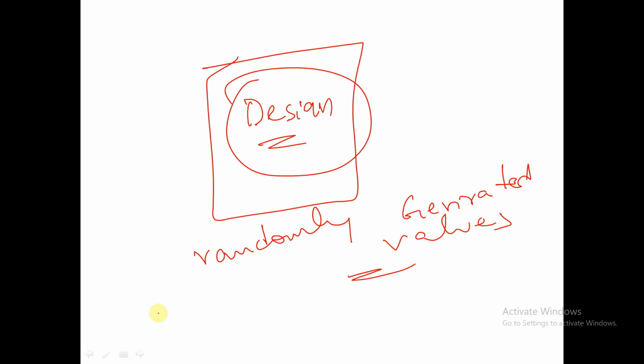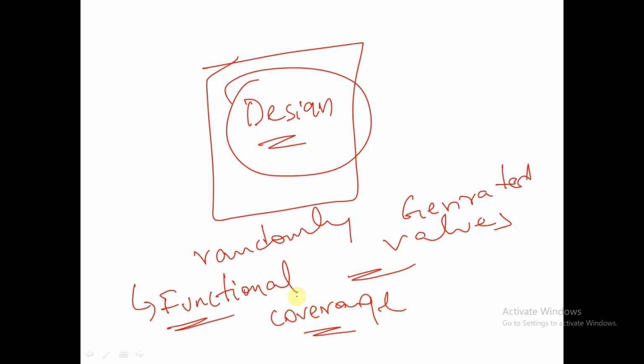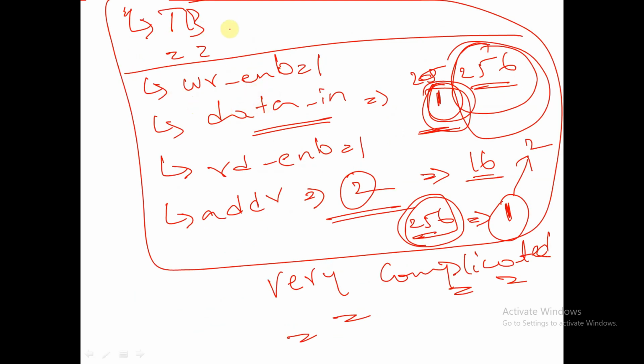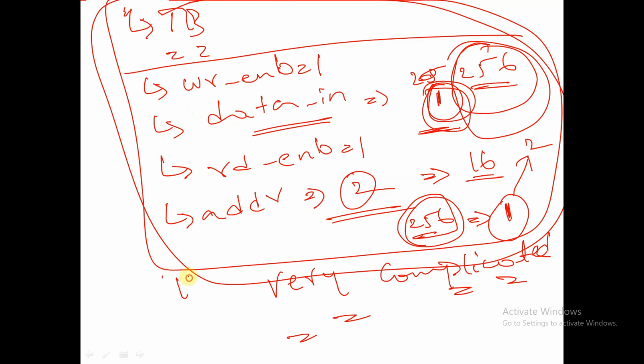And there is another concept called functional coverage. We are going to check whether all the possible scenarios, all the possible test cases are tested or not. So what we write in Verilog is basically a directed test case.